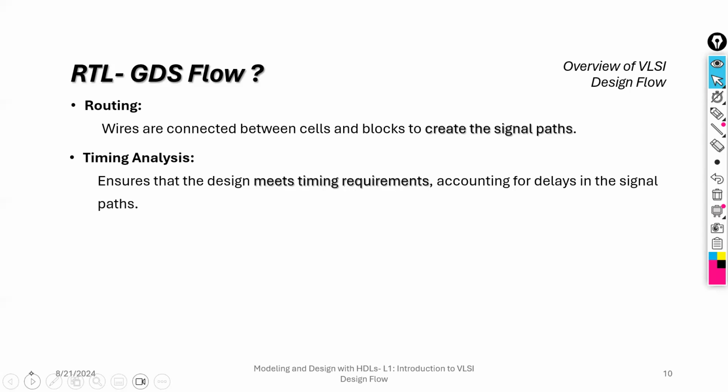By which we are able to say whether we are attaining the signals at the right time or not. We can verify with the help of the slack. Positive slack is required. There should not be any kind of negative slack in this design, right?